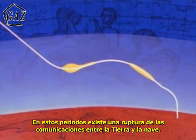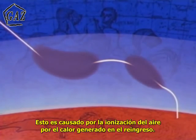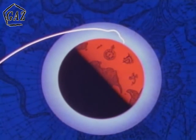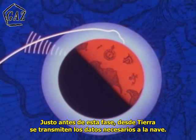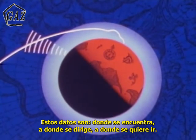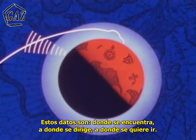Yet during this period, communications blackouts exist between the ground and the spacecraft, caused by the ionization of the air from the heat of entry. Therefore, entry will be entirely controlled through onboard computations. Just before the entry phase, the ground will transmit the necessary data to the spacecraft, that data being where you are, where you're going, where you want to go.